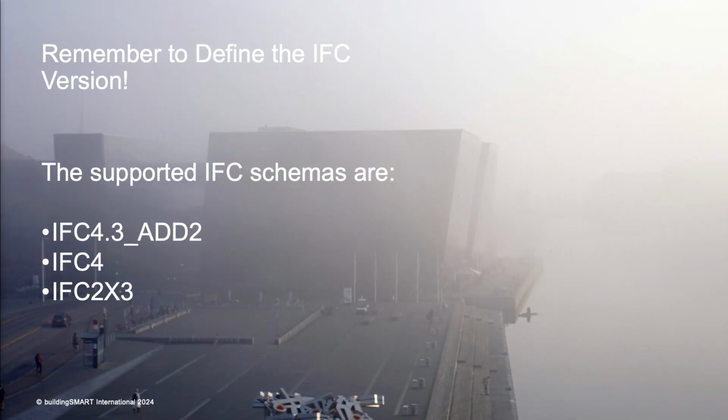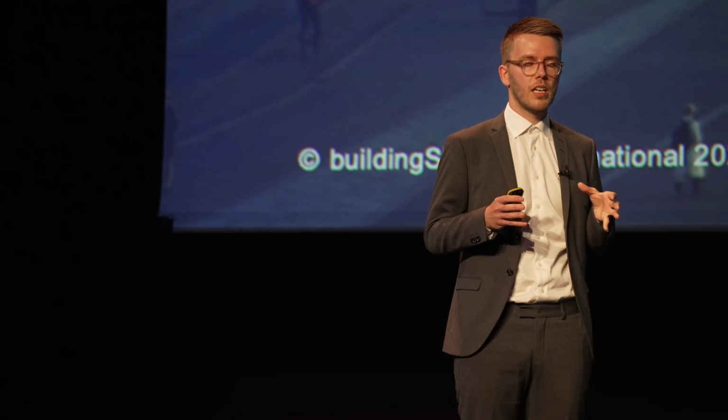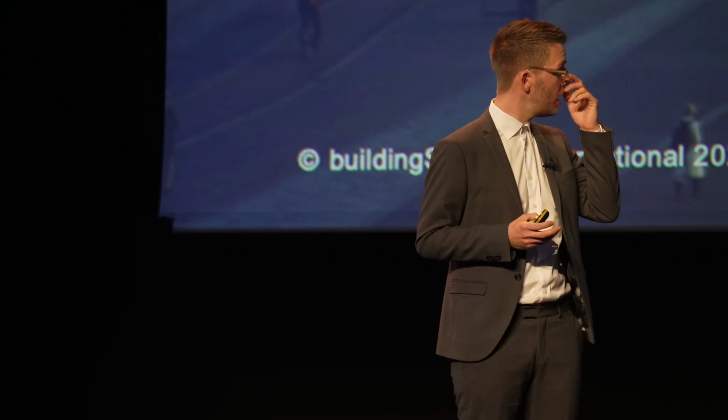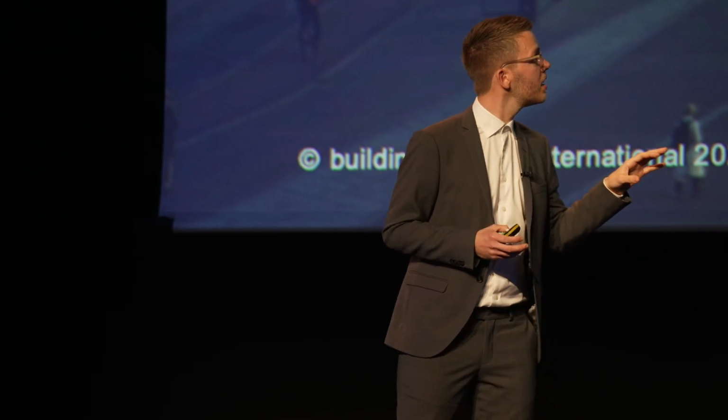So when we talk about IDS, the IFC version is important. IDS actually supports those versions of IFC, but often I see in Denmark that the version of IFC is not defined in the agreements. And this is important because in Fehmarn's context, it's important that we use IFC 4 or IFC 4.3.